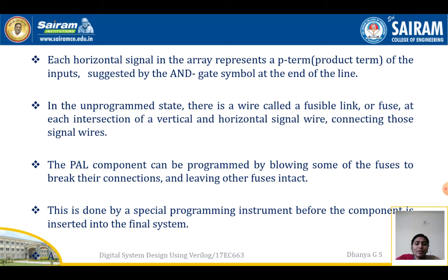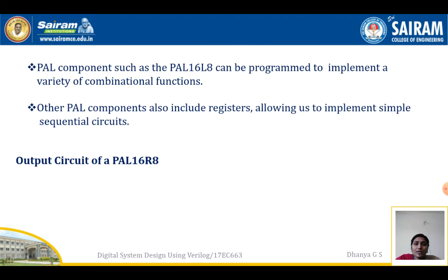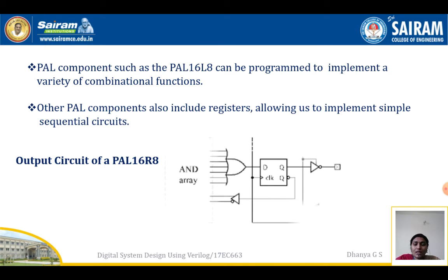I already discussed with you the special programming instrument in the initial slides. We require some programming instrument to do all these functions. PL components such as PL16L8 can be programmed to implement a variety of combinational functions. Other PL components also include registers, allowing us to implement simple sequential circuits.